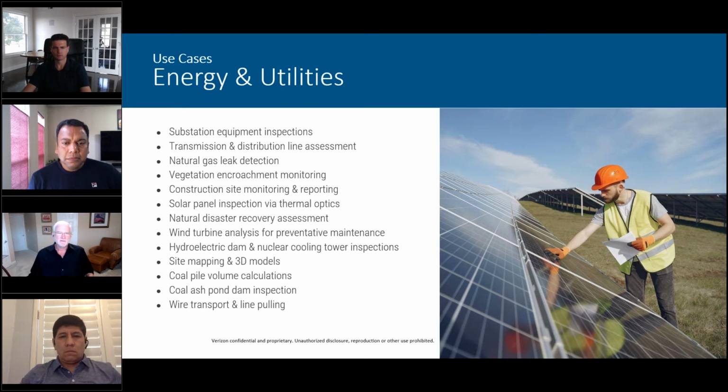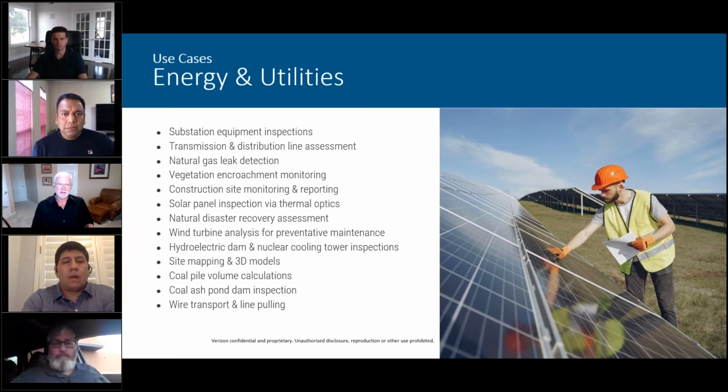If you have a thermal camera on a drone, you can just go right above that image, and you can actually go to even a section within the panel and tell by the temperature difference which panel's bad. And so everybody that's doing anything in solar construction and maintenance are using drones today.